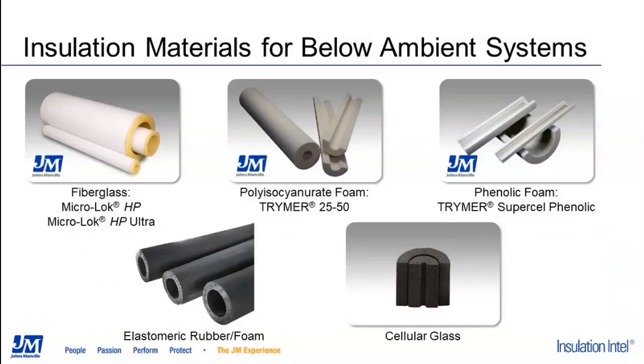There's fiberglass pipe insulation, like JM's Microlock HP products. Fiberglass is a sand-based material. The pipe insulation sections come pre-formed, pre-split, and with a factory-installed vapor retarder. It's also worth noting that fiberglass is sold with butt strips, which are used to seal the seams between installed sections and are a key part to completing a sealed system.